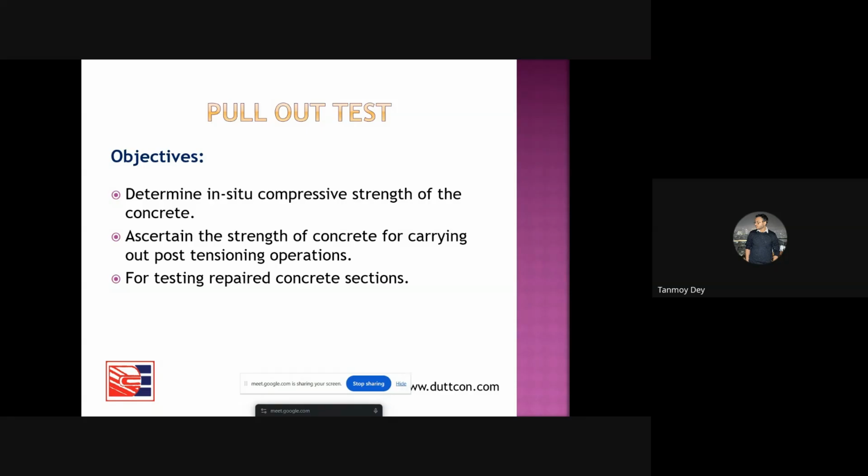When magnetic lines of force are superimposed on each other, say 2-3 layers are there, one line of force is getting imposed on others. This particular result may not give us the true picture. That's why the rebar locator is, most of the time, not good predictive in nature. So this can give the idea of the cover, how much depth is there. This much is all right.